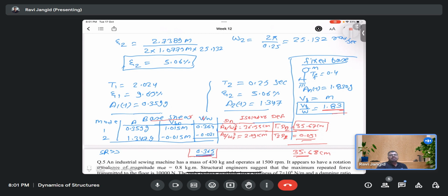But if you are interested in the floor acceleration and floor displacement, then you have to put the sensor at each floor. We have accelerometers, and it is a three-floor structure. In the result, we have to find the modes by our analytical method.